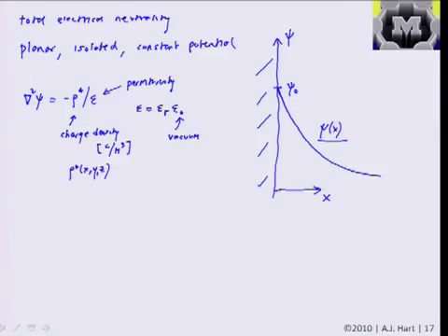And so we're going to jump right away to saying, well, of course, we have a 1-dimensional problem here, so we can make our life a lot simpler. And we can just say that the second derivative of the potential psi in our x direction is equal to the charge density distribution rho of x divided by epsilon. So also our charge density function is one-dimensional.